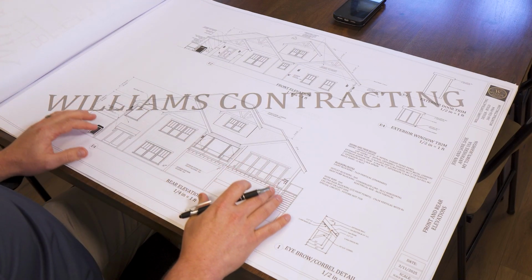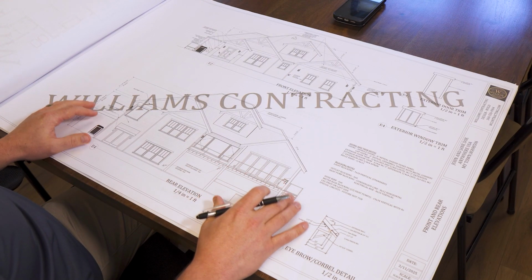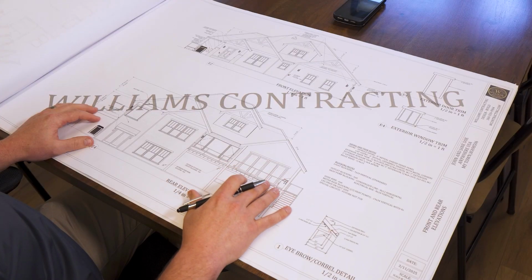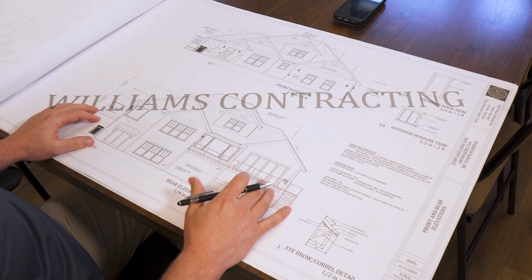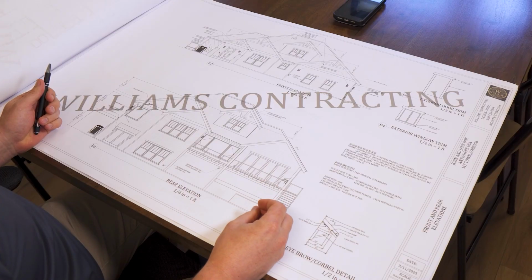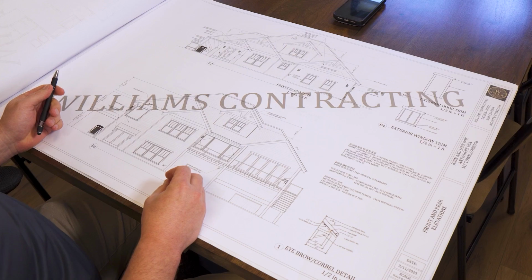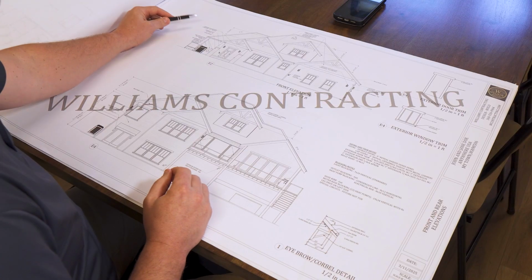Sheet 3 is where we get into a lot more detail. This is our elevation. Sheets 3 and 4 contain the elevations of all 4 sides of the home. This is where we start to put in a lot of nice detail and callouts. These are important. They communicate to the construction team as it involves the framing team, the siding team, the electrical team, and the mechanical team. What's happening, what's going on in the home, as well as the design elements for the window package. Let's look at this example.